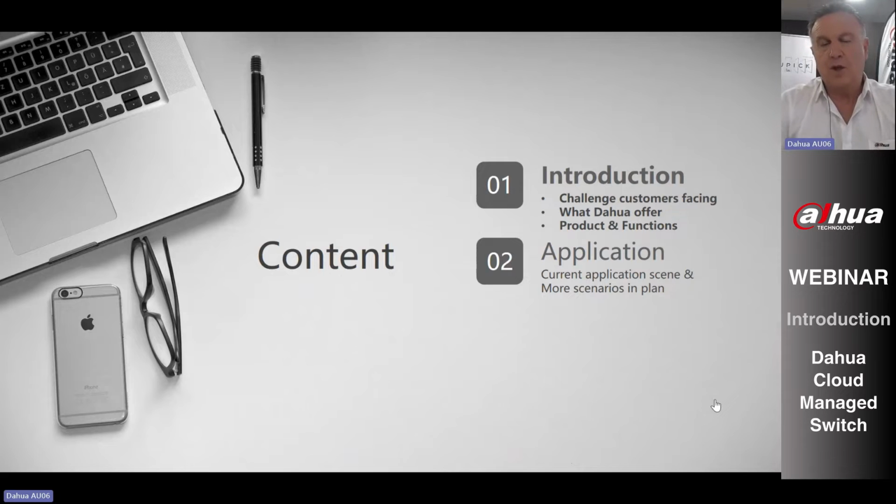You are an installer, you are a system integrator. Congratulations on your experience in putting together CCTV systems. Dahua congratulates you on this example where you have secured a project with a large number of cameras, say 30 or 40 cameras. You've got your Dahua NVR and you have used a number of PoE switches to connect the additional cameras beyond the 16 PoE ports on the back of that NVR. Let's say this remote site is about 100 kilometers away from your normal operation center point.